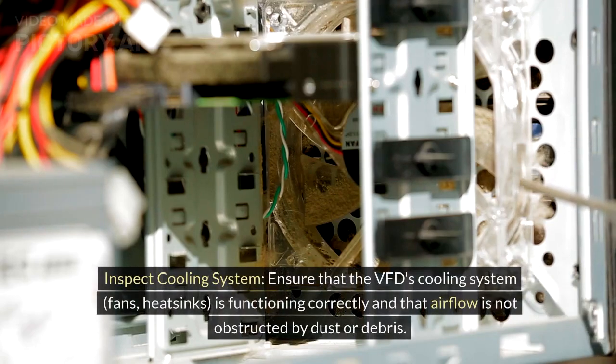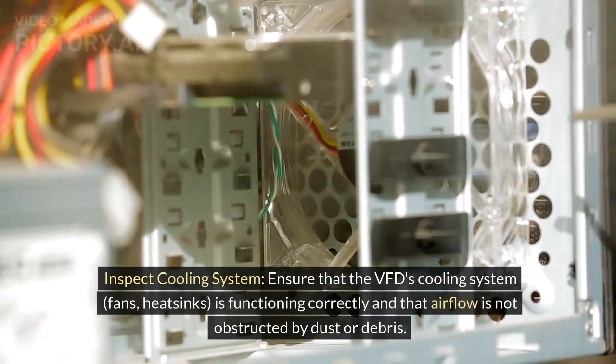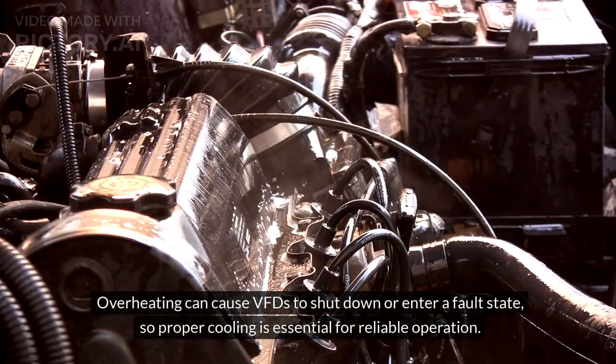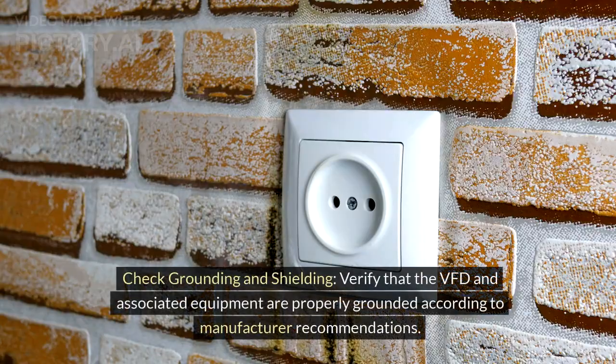Inspect cooling system. Ensure that the VFD's cooling system, fans, heatsinks, is functioning correctly and that airflow is not obstructed by dust or debris. Overheating can cause VFDs to shut down or enter a fault state, so proper cooling is essential for reliable operation.